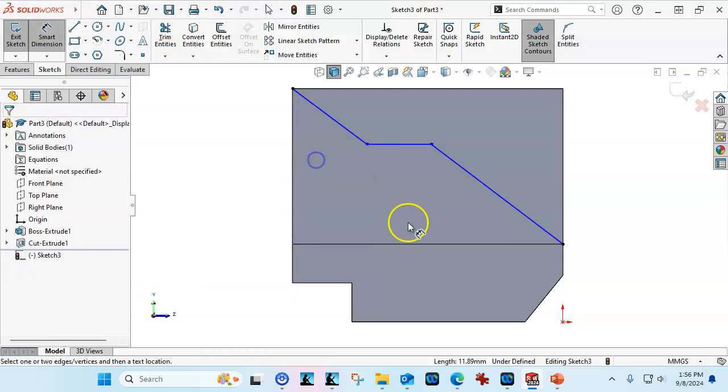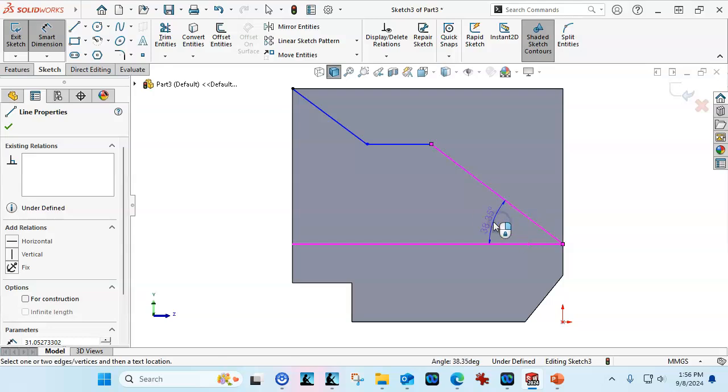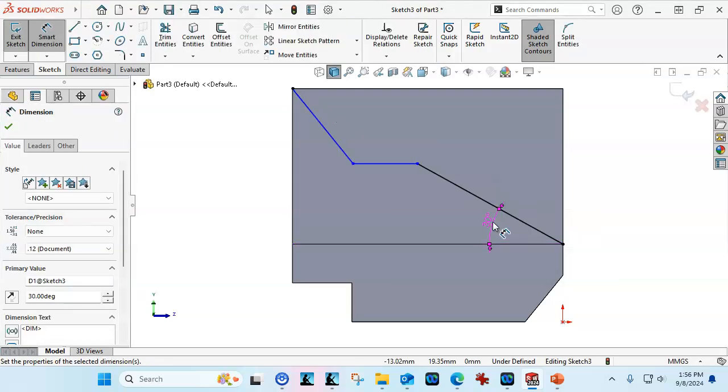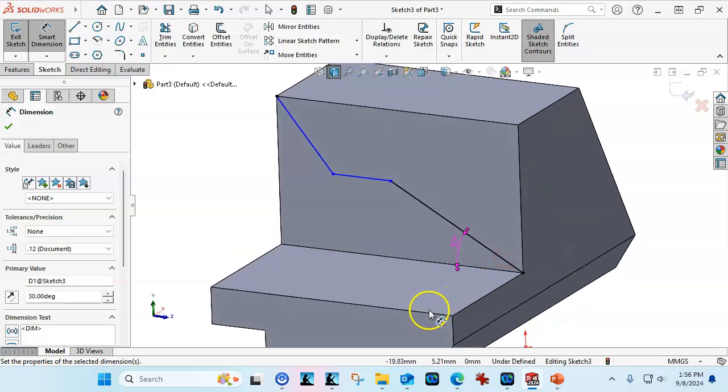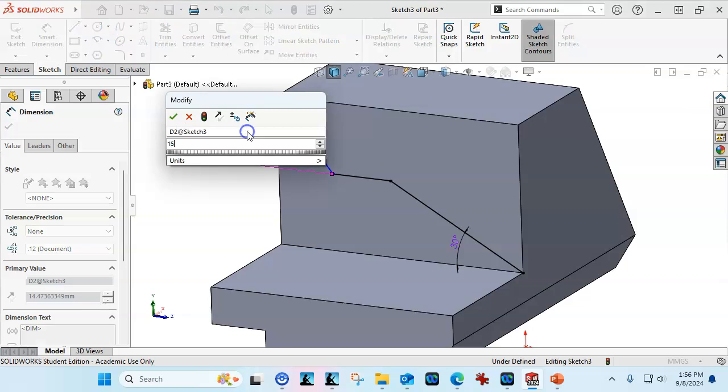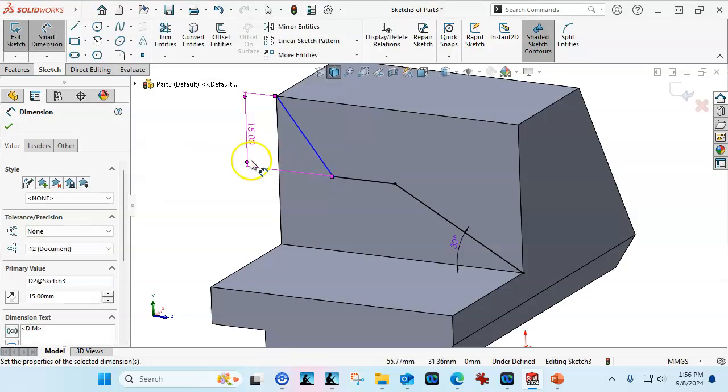And that face is 30 degrees. So here, because we are projected into that sketch, even if I'm grabbing this leading edge, it would be the same as that edge, and it's able to solve for it. All right, and then we can go to 15, see what else we need. We have an angle of 30.